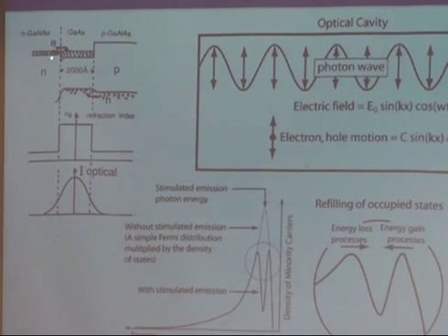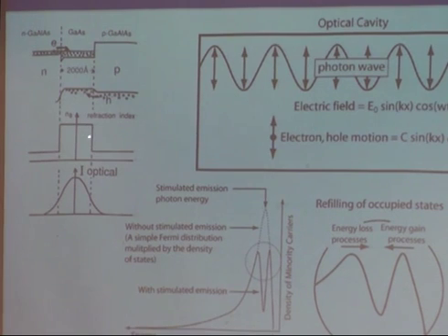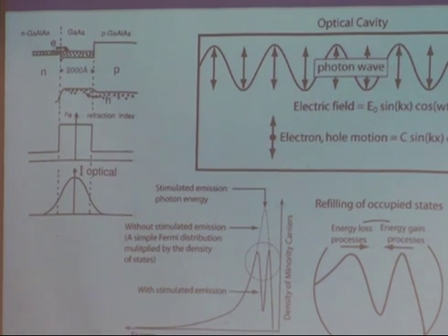You're injecting electrons from one side, and you're injecting holes from the other side. The double heterostructure gives you a large conduction band offset here, which essentially doesn't let electrons spill out into the n side; it blocks or reflects them. Similarly, for holes, you need a large valence band offset here, and you can reflect the holes. If you have read Herb Kroemer's review article, you have seen nice pictures of why this is useful, because you need to inject a certain threshold amount of electrons and holes to create lasing. But if you don't confine the electrons and holes, they will spill over, and you won't get that threshold at all. So the double heterostructure really lowered the threshold for lasing by huge amounts.